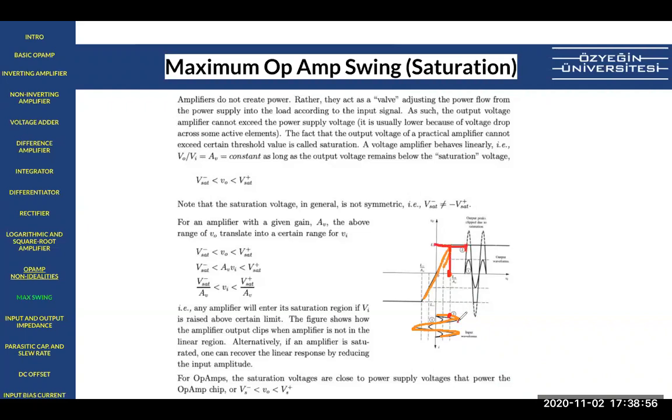But when we came to this peak, the peak tells you, hey, now we saturated, so we cannot go further. This one is the amplifier characteristic curve. This one is two different inputs to show you how the inputs can have different amplitudes. And the corresponding x-axis, putting it into the characteristic curve, you get the output.